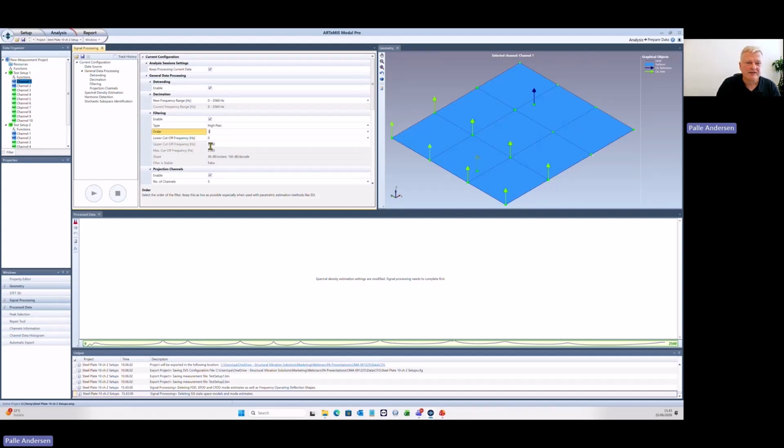And then let's say now we are at a maximum frequency of 2500. So if I put something like, I don't know, 10 Hertz here, I will remove everything that is from 0 and then on the way up to 10 Hertz in this way here. And that will be something like a slowly growing trend like this. That one will then be removed by this operation here. And that will dramatically help the analysis, that we get this low frequency thing away from the data.